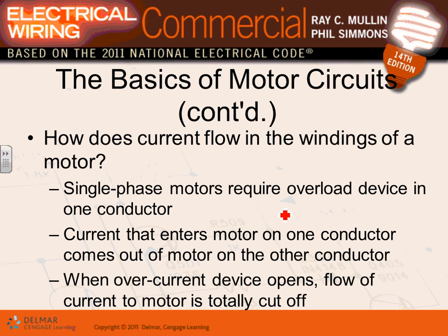So overload: this is just about how the current flows in a single phase motor. The current in a single phase motor, guys, goes out on the hot and back on the neutral. So if you interrupt the hot conductor, the ungrounded conductor, you will interrupt the flow of energy. So you need only one overload protection device in the ungrounded conductor.